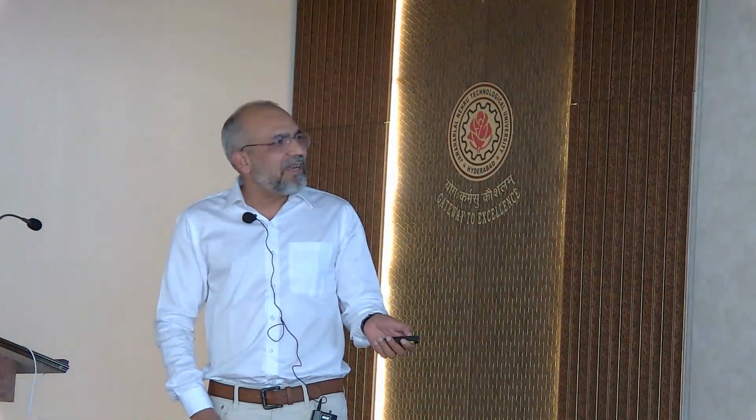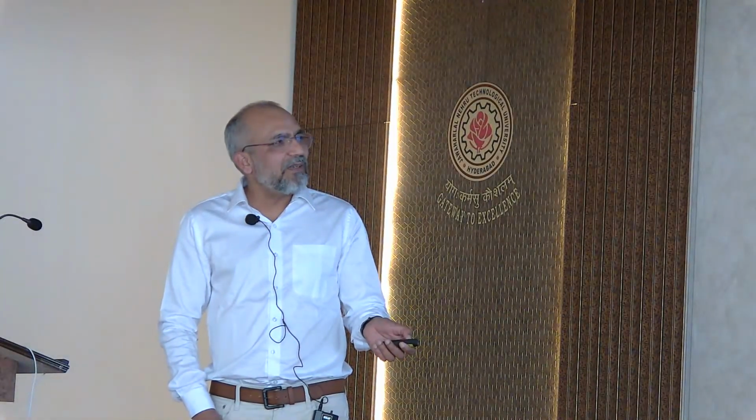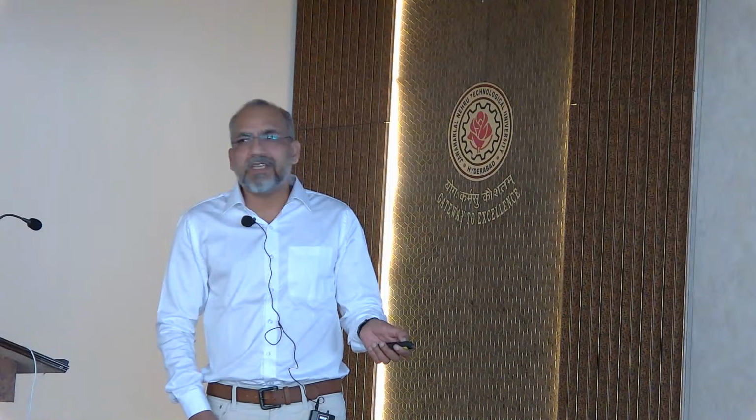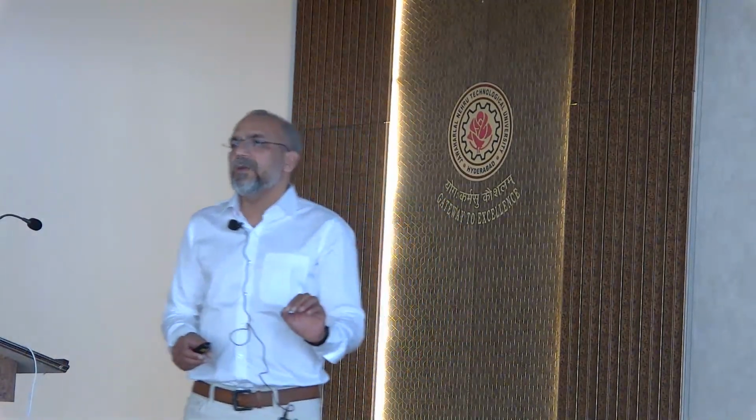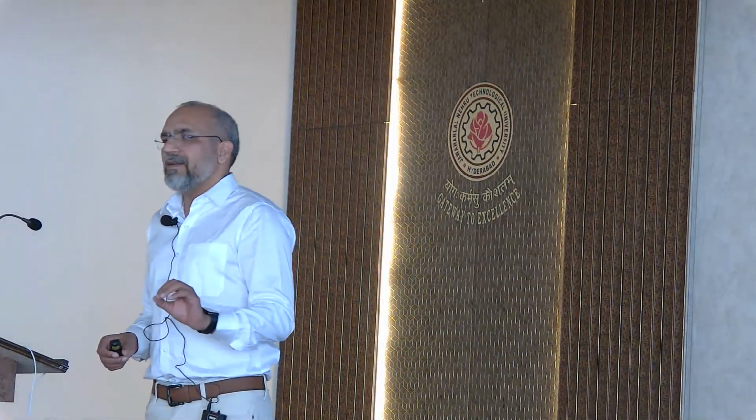So in this one, that's a tube here, and in the tube we should have these two blocks, ceramic blocks. And when we were setting up the CVD device, I took them out. And every time I was running the experiment, there was no graphene on the copper. One day, just to see, I flipped the copper. On the bottom, there was a lot of graphene, but on the top, no graphene. And the reason for that was how you tune the microenvironment on the copper surface.